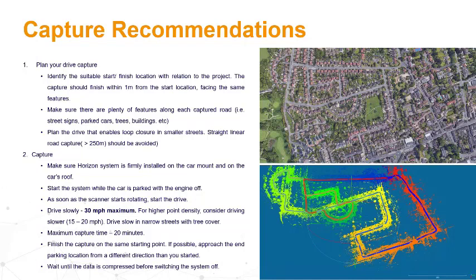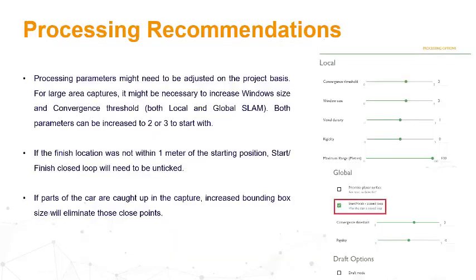So it's better to plan a survey in the time where there is not so much traffic. If there is a couple of cars going around, it should not be so significant. But if you have an option to avoid it, that's always better. So consider also driving not only in the loop, ending the loop on one place, but even within the project, it's better to have more loops, and then also come back to the position where you started, ideally from another direction than when you started your projects.